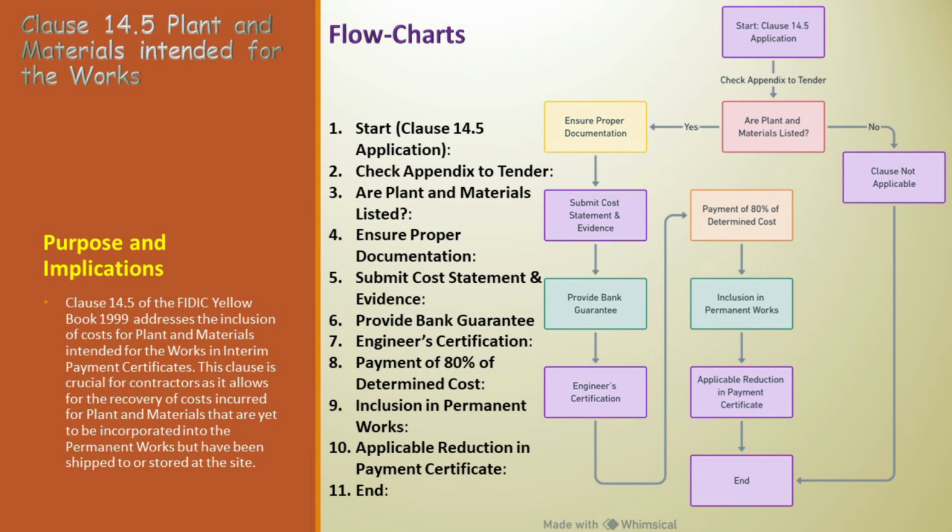Engineer certification. The engineer's certification marks a critical step. The engineer certifies each addition, confirming that the plant and materials meet contract requirements and are properly stored and protected on site. Payment of 80% of determined cost. The financial aspect comes into play. The engineer certifies the payment of 80% of the determined cost of the plant and materials, including delivery. Inclusion in permanent works. The status of materials evolves.